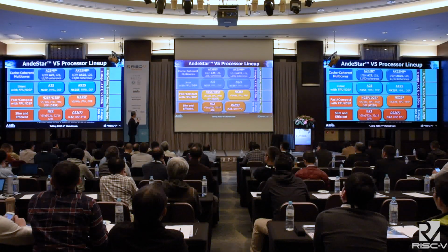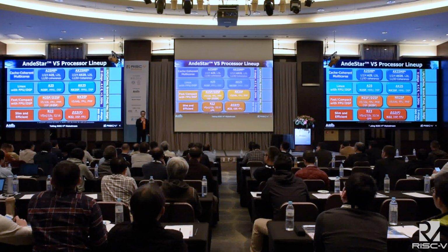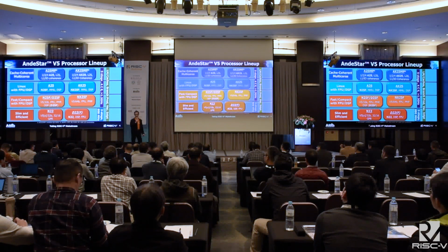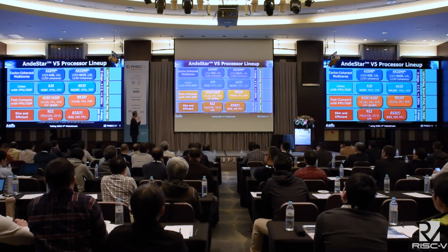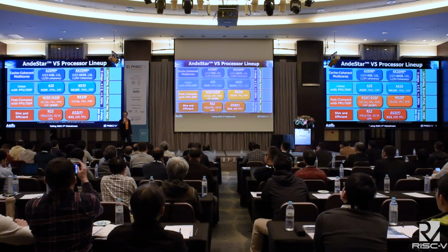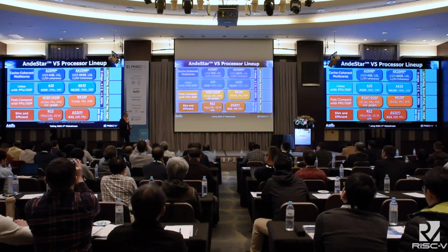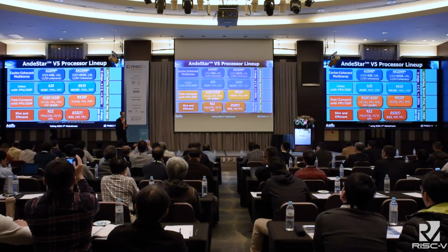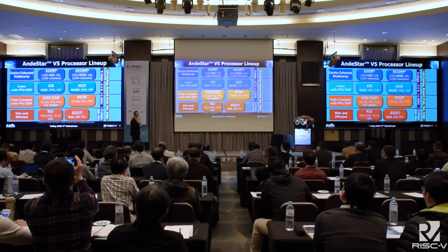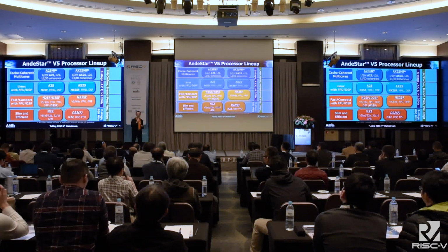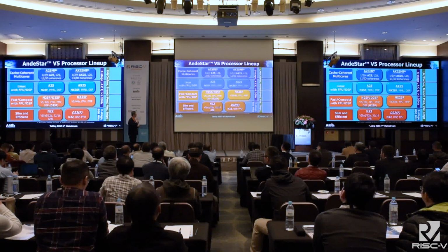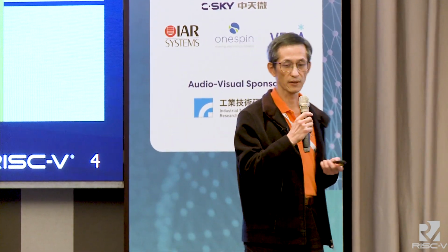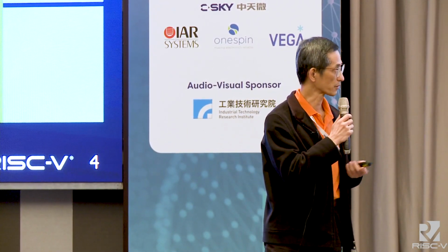And going up, we have a 5-stage pipeline core, which is a fast and compact core with floating point or DSP as optional. And going up, we're adding an MMU, so it can run Linux. And then going up, we have a core running up to four cores in parallel with cache coherency. The core with X is for 64-bit. Otherwise, they are the same. So they have a very uniform feature set: local memory, branch prediction, vector interrupt, and so on.